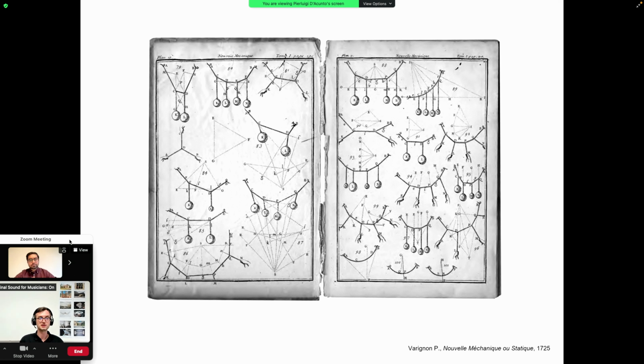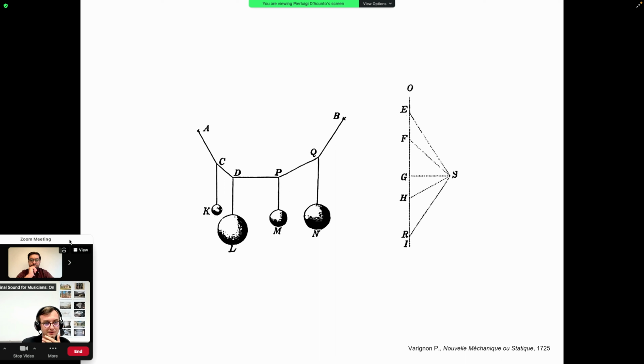and in here we see all these drawings, which represent cables that are put in equilibrium by adding different masses. The masses hanging from the cables force the cable to take a very specific shape, a shape that puts the infinitely flexible cable into equilibrium. Some of you might have studied this also at high school, and the principle is very simple. Given a structure in equilibrium, like the cable on the left, it is possible to represent its equilibrium with graphical means, specifically with the diagram that we call the force diagram, which we see on the right. So we take a structure in equilibrium.